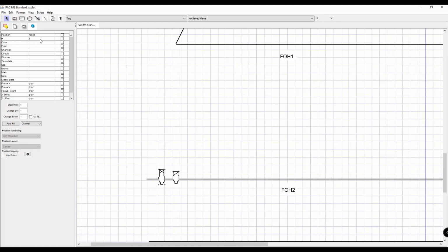Now, the number of the lights will be automatically assigned whenever you import something, so I usually uncheck that. Color is your gels. LX Free is really good in the way that it works well with the Rosco gels. So if I was to do Rosco 2 and then hit this little check mark, you can see that it turned amber, which is very, very helpful, especially when you're using things like top light or whatnot.